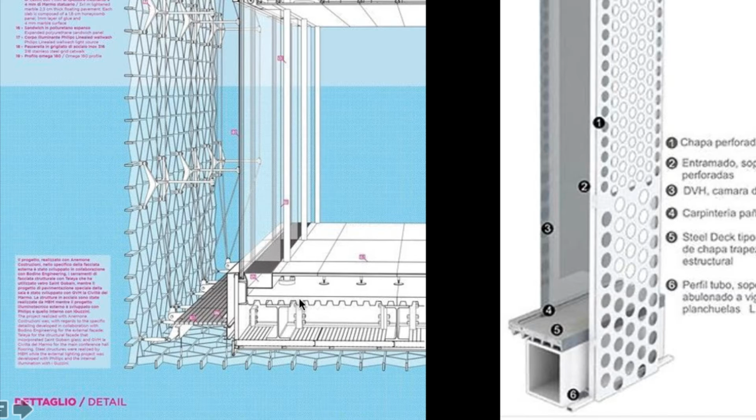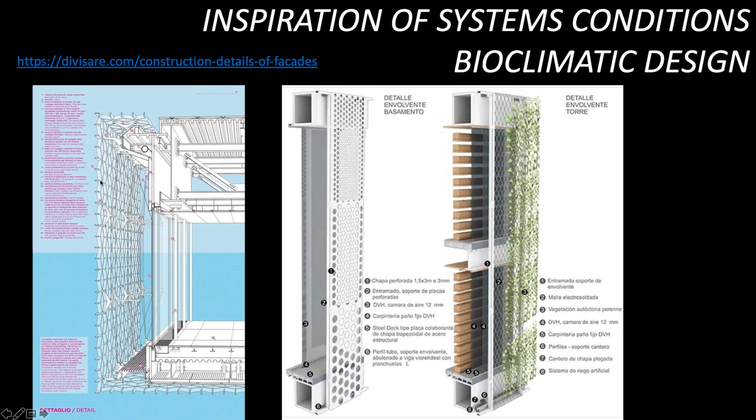If you think about this, concrete composite decking is a pretty solid material. And so we may have issues running plumbing, running electrical. And this kind of a raised floor allows you to really run those systems up above the floor and to change things out, to be able to access those systems fairly easily. We see some thermal devices at the facade to keep the glass from building up condensation. We see some really quite beautiful truss devices on the outside, which are holding these brackets, which are then holding the screens. So I think you want to think about what's the layering?